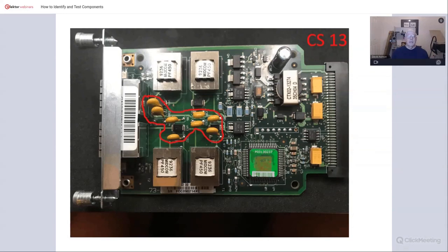Right, these funny looking capacitor things. I thought when I first came across these that they were capacitors, but they've got a marking on called X017. Now, from experience, I thought, oh, these are polyfuses. They're pretty thick for capacitors. Polyfuses tend to be a bit thicker.